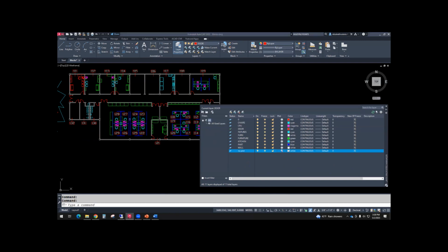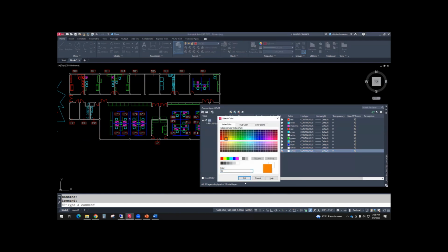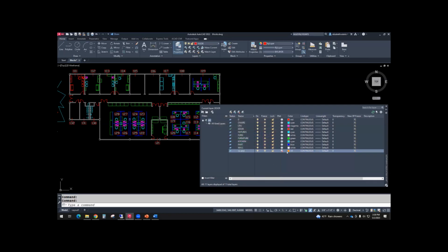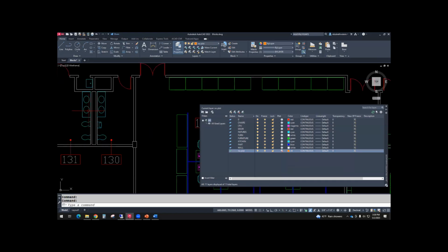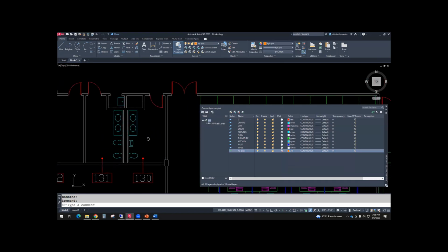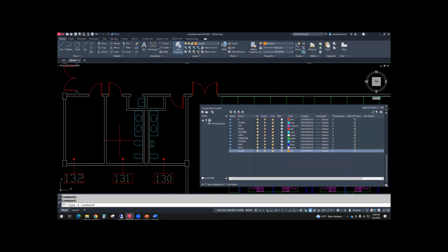And they pick some color that they don't use very often, maybe orange. And what this is used for is just for your own notes, right? Something that you want to remind yourself, or maybe it's helping yourself sketch something, but you don't want to print that by accident. So for example, I'm looking at this bathroom and I notice this is the boys' bathroom, has a urinal. This is the girls' bathroom, no urinal, but a girls' bathroom usually has walls and doors.